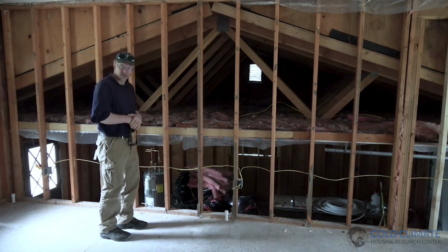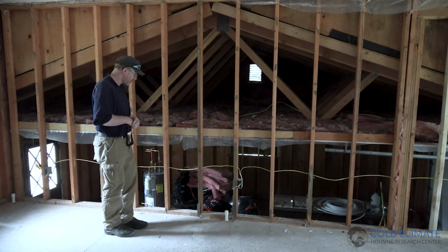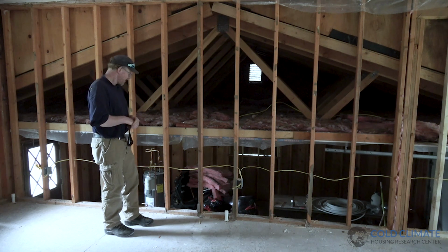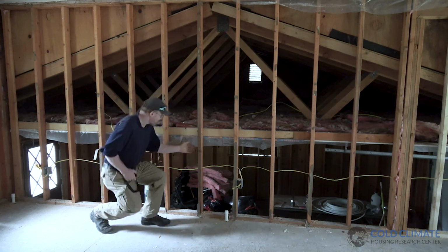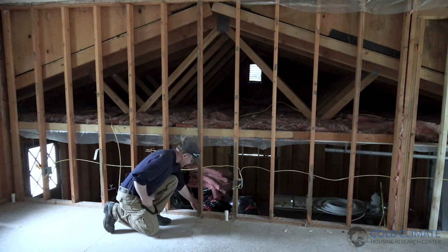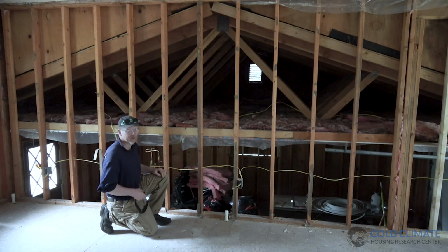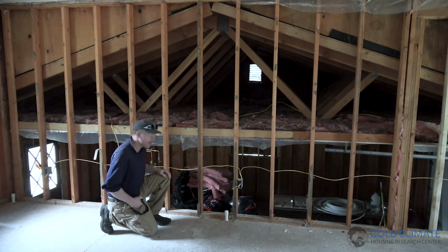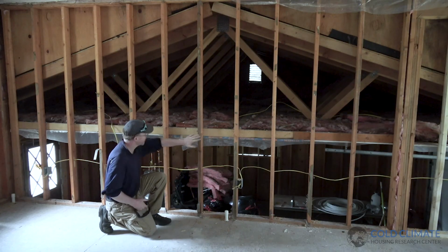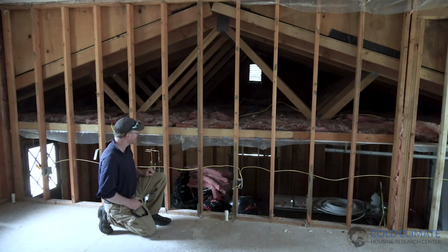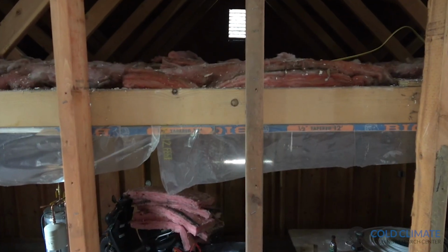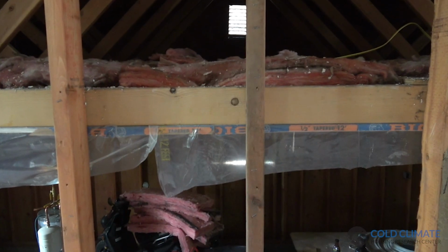And unfortunately, this is really common in split level older homes. And even nowadays, we're seeing this problem continue. What's going on in this case is the vapor retarder from the garage ceiling went and sealed down here to the bottom plate. It was just stapled on because this predates the sealing methods we use nowadays. But in addition, on the front side, there was a kraft-faced fiberglass batt insulation, but there's no transition for our thermal and our pressure boundaries to carry through this wall.